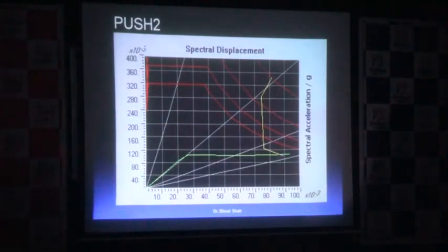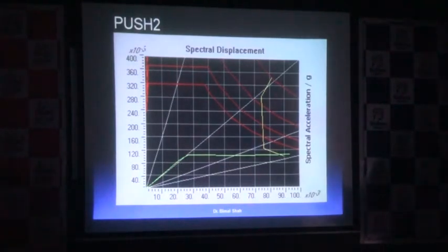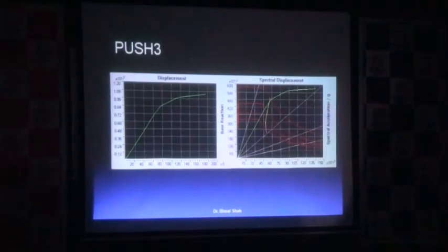At that point, when you keep on pushing, your hinges can go up to even blue color, or even green color. But that is not mattering. What is mattering is that at the time when your performance point is met, what is the state of the hinges. If it is in the immediate occupancy stage, you can say that the building is not going to get damaged. Okay, so this is what happens.